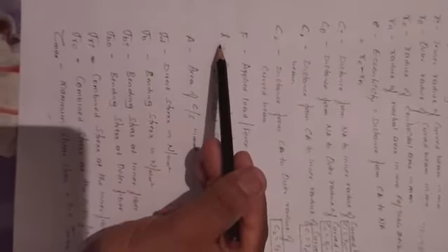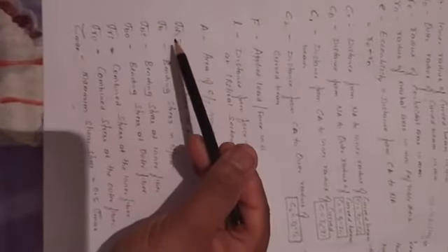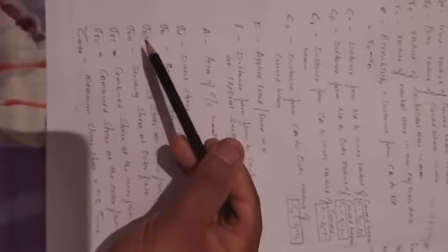Then F is the applied force, instead of applying an external bending moment. Later we'll discuss what L is. L stands for the distance between the line of action of the force and the central axis of the section. A is the cross-sectional area. Sigma stands for stress: direct stress, bending stress at the inner fiber, bending stress at the outer fiber.